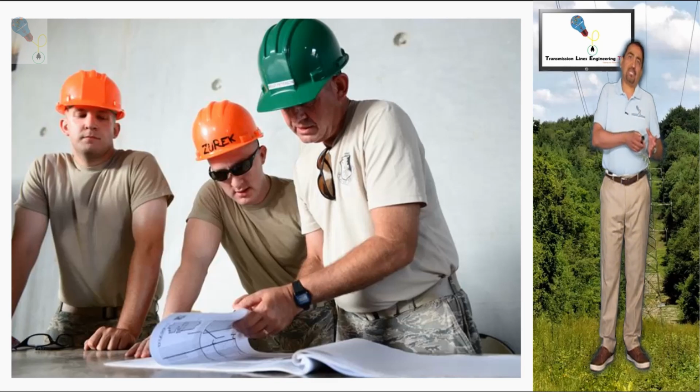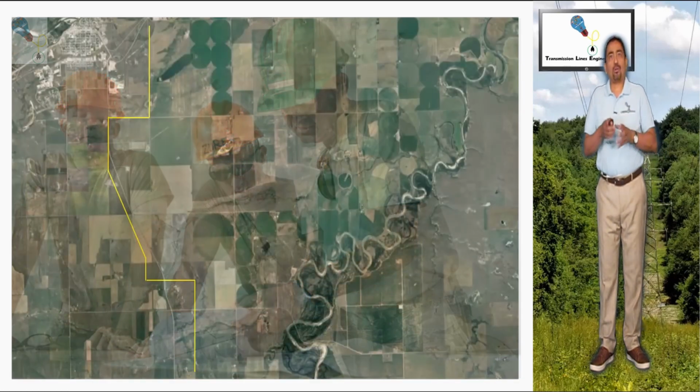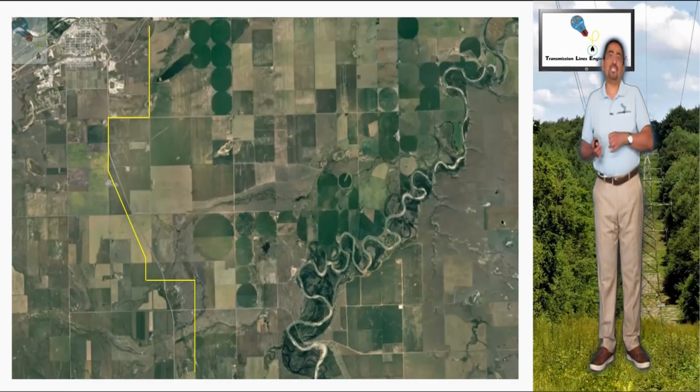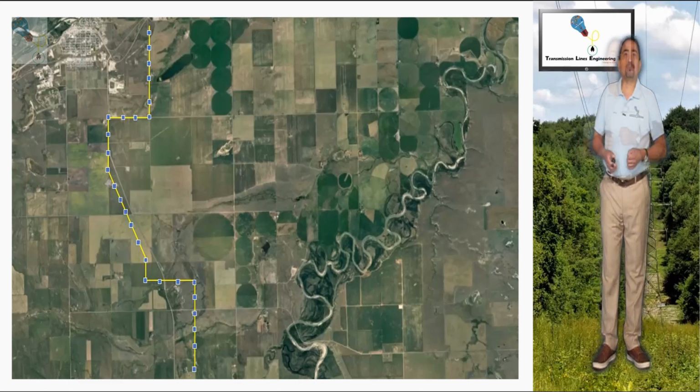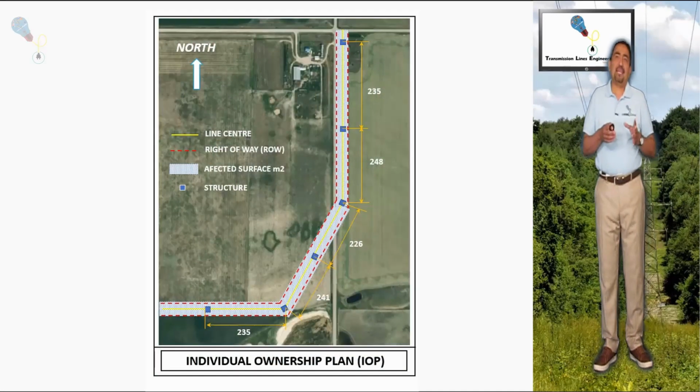So, as step number 6, the structure locations previously made during the evaluation stage of possible alignments are reviewed again based on the design restrictions document or the red book to make the appropriate adjustments to the structure locations or structure heights and types.